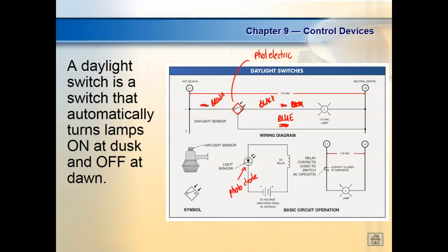Your low voltage inductive sensors are going to be 3-wire sensors. Those sense metals. Your low voltage capacitive sensors sense liquids and solids. They use the same color code. Then photoelectric, I can bring out the temperature sensor, and it'll be a 3-wire sensor, same color code. I could bring out the pressure sensor, and it'd be the same color code.